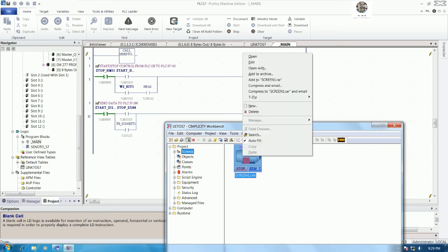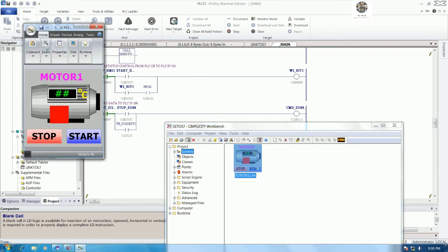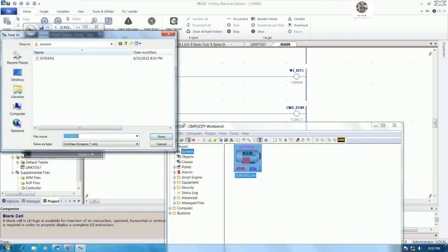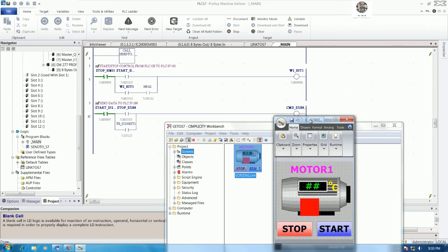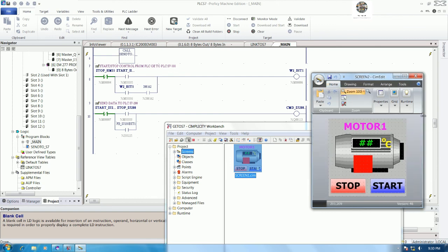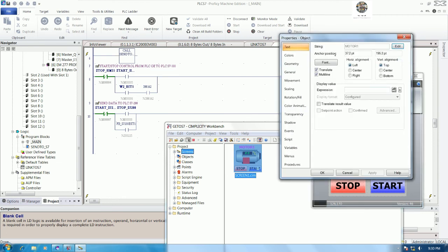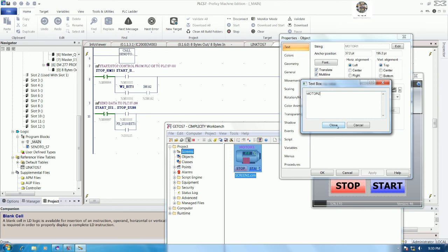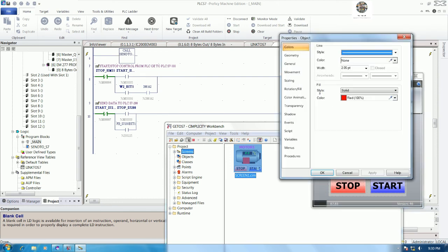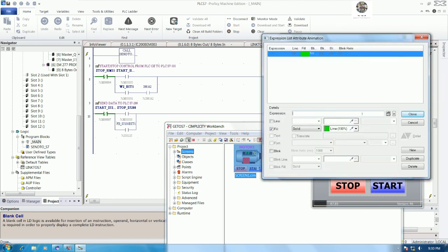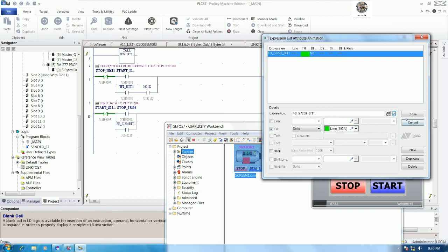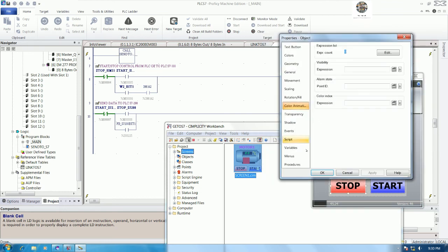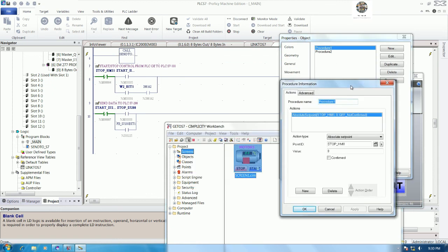And then we can create a screen, yeah, we can edit and then save as one more model. Example screen 2, and then we can edit, yes. So this one there is no temperature, right? So I will delete motor 2, and for the status I will use the bit that we already created, right? So feedback from S7-200 bit 1, yes. If it's true, it will green.